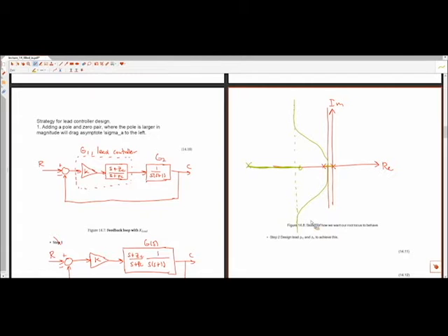Yes, Carson. So wouldn't you want to move that pole way far to the left so it doesn't oscillate too much? So just make it more like negative 1 billion and make the zero 0. So negative 1 billion, that would be getting back to PD control, right? The pole location determines our filter, what frequency we filter, so that would be like having a really high gain feedback with no filtering at all.